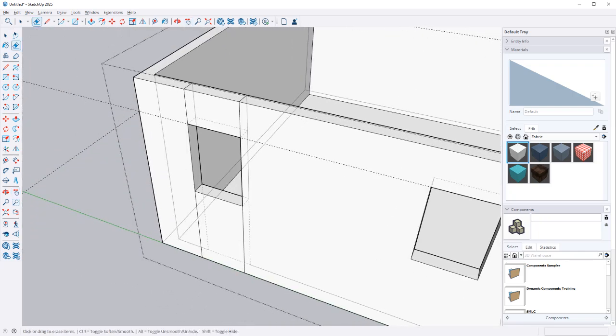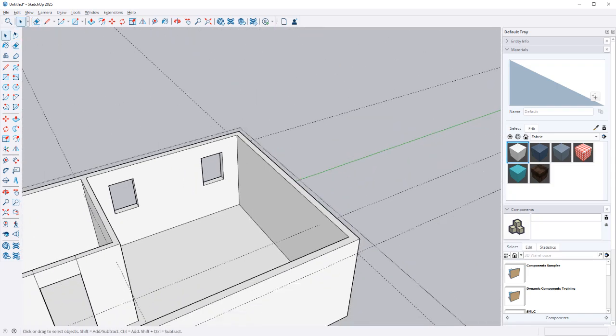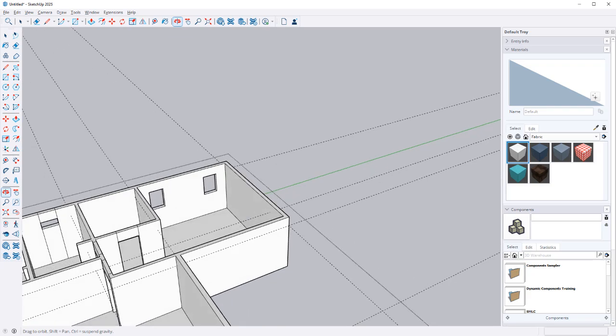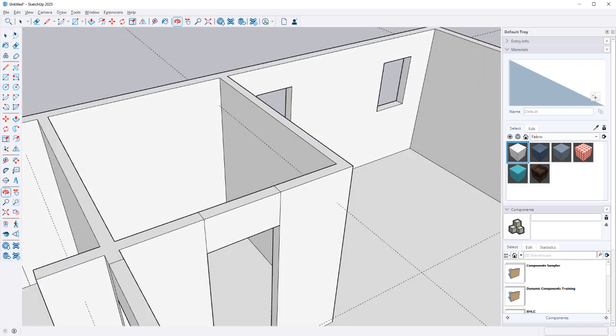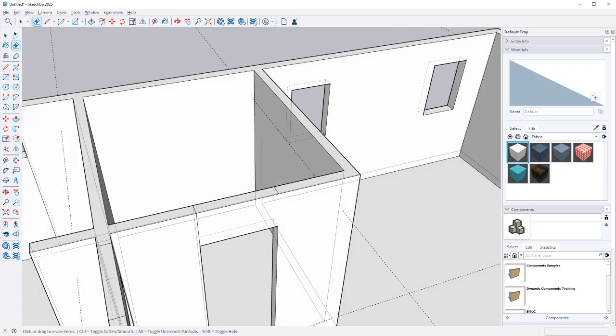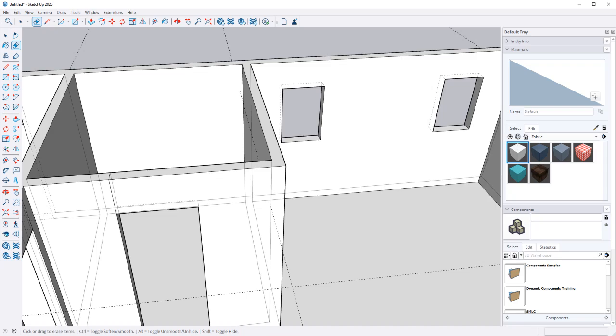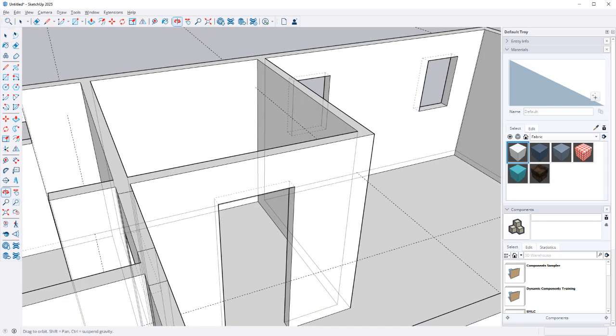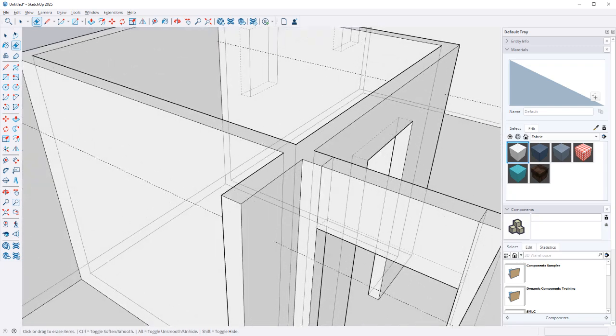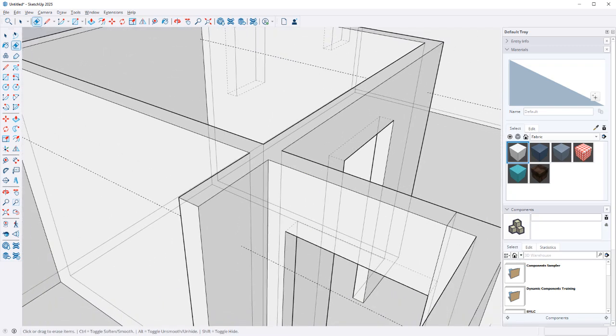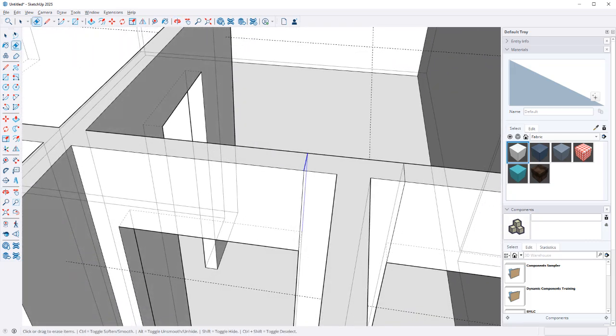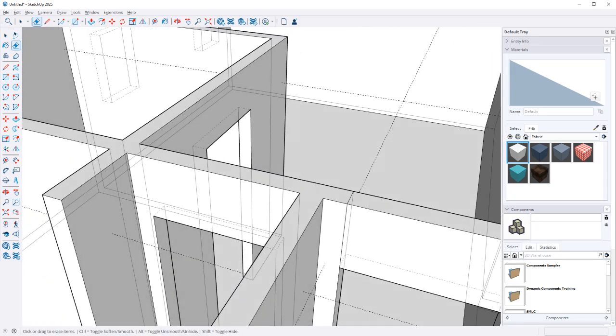The reason why you want to get rid of these is, if you remember when we were setting up the materials, anytime you have a line that subdivides a face, that creates a new face, and it's more geometry that you have to apply materials to or work around. So we're just trying to keep clean models. I just zapped something there. So just keep an eye out when you're using K for anything that's behind what you're working on, especially when you get in areas like this. Get in there, make sure you're getting the right lines, rotate the camera if you're worried about it hitting anything else. And yeah, I just got one of the other ones there.